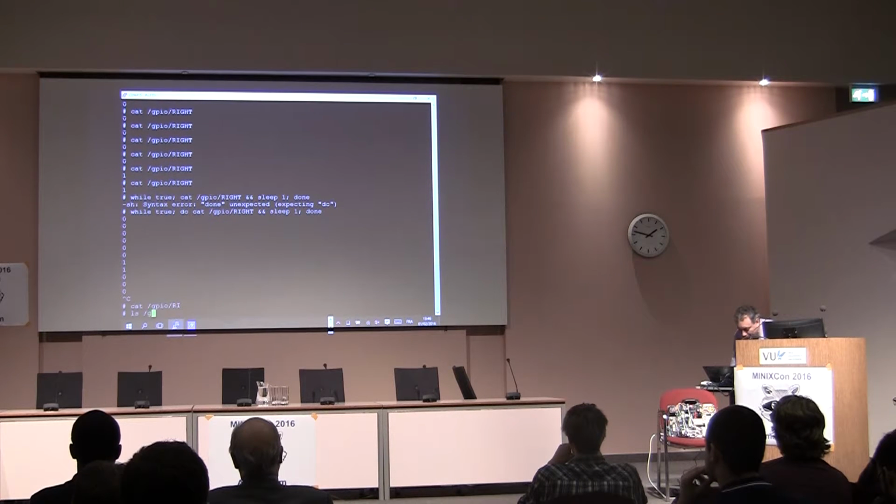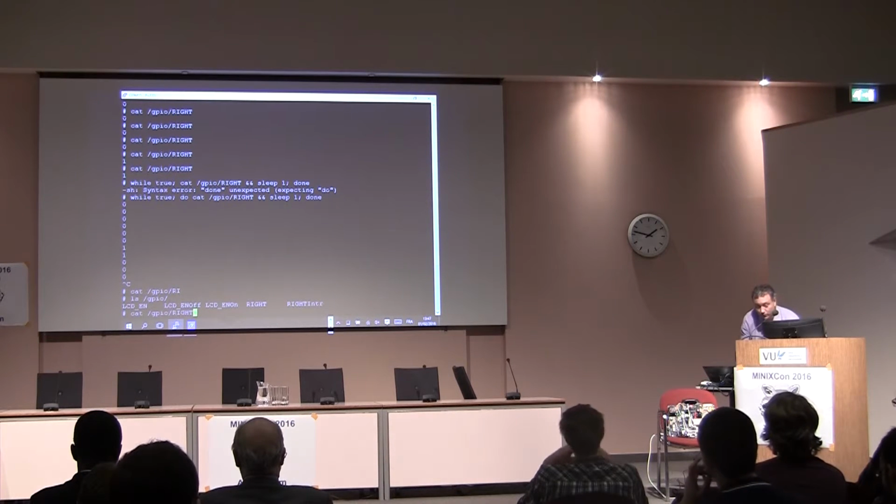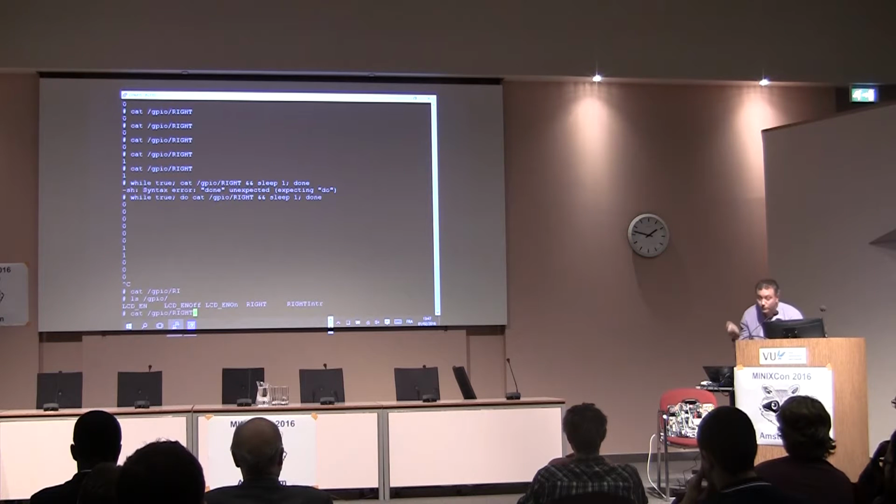So basically, don't forget, what we have in the GPIO file system are these pseudo devices, I don't know what to call them, targets, I guess. And before we were using the write, that was reading from the GPIO, and it was printing a 1 if it had a voltage, and now we're going to write the GPIO. So we're not going to use that target, we're going to use on. And I'll just sleep for 2 seconds so that we have time to switch to the other screen.